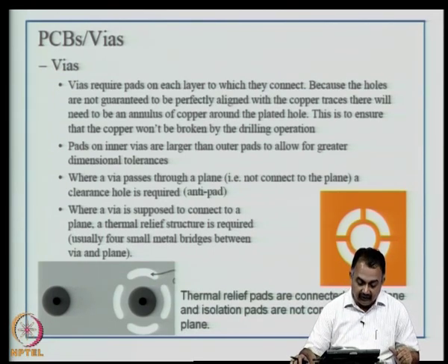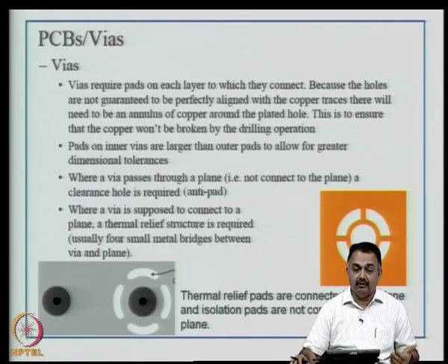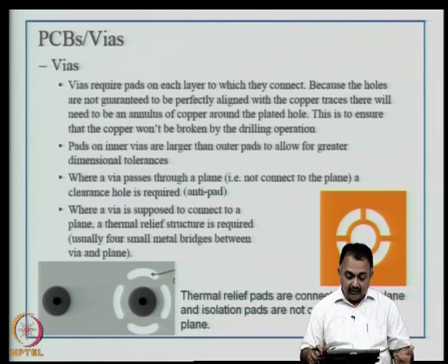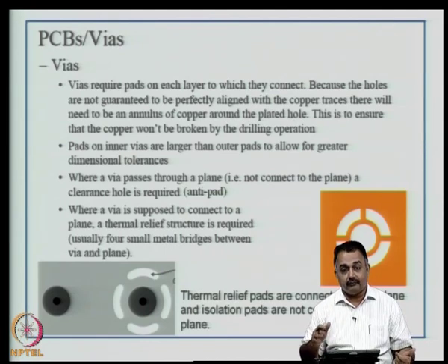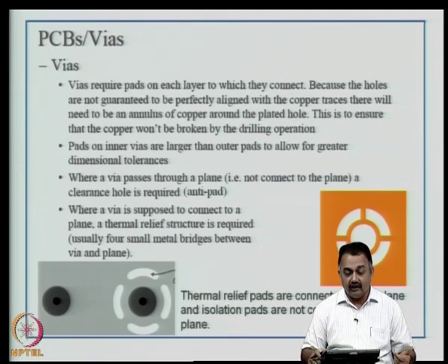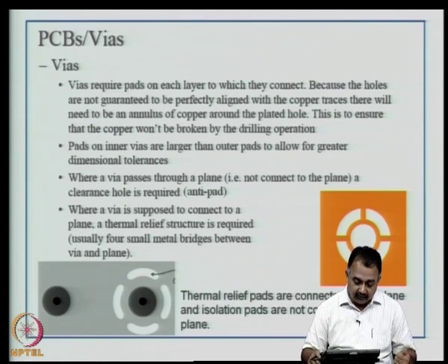Pads on the inner via layers are larger than the outer pads, because again the dimensional tolerance will be greater for aligning inner layer boards of a multi-layer board.